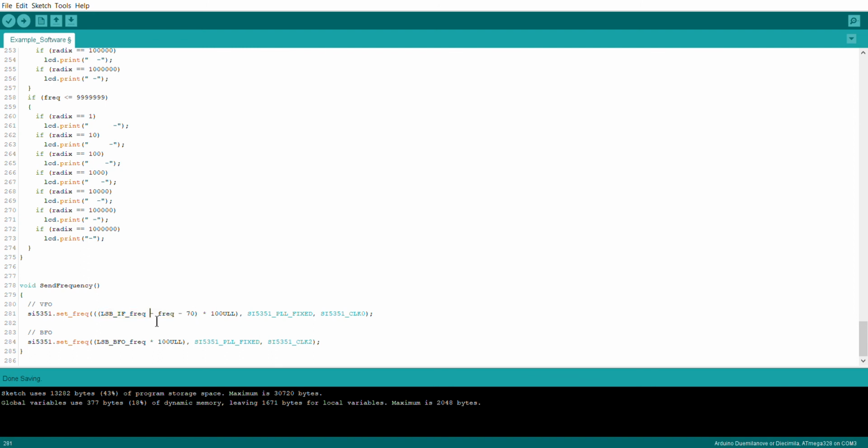So that may be, there are cases where I have, that would be a plus, and you'd put on the high side. So the variable frequency oscillator will actually be above the intermediate frequency. But suffice to say, this is where you do all those manipulations to make sure that the VFO is sitting in the right place. We'll come back to 70.